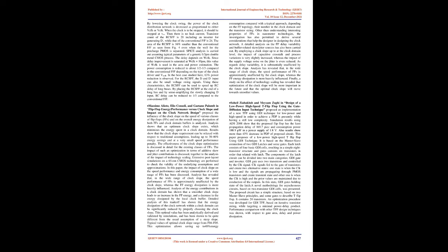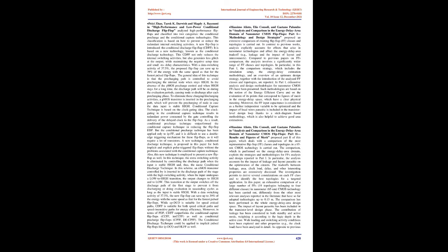The general idea of this technique is that the precharging path is controlled to avoid precharging the internal node when the input stays high. In the absence of the PMOS precharge control and when the input stays high for a long time, the discharge path will be on during the evaluation periods, causing the node to discharge after each precharging phase. To eliminate these charging/discharging activities, a PMOS transistor is inserted in the precharging path, which will prevent the precharging of the node in case the data input is stable high.